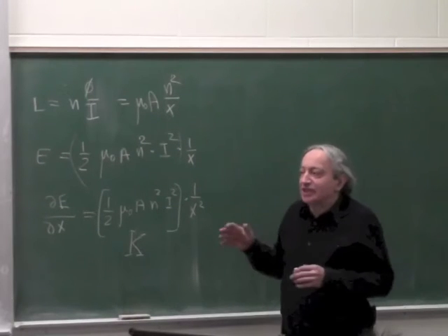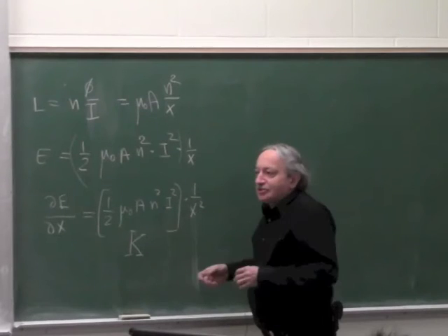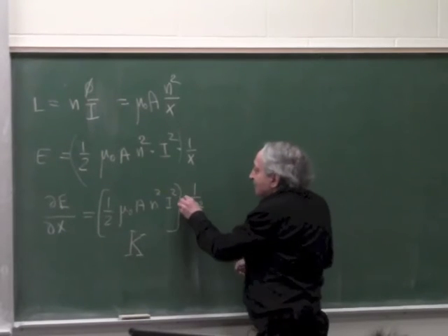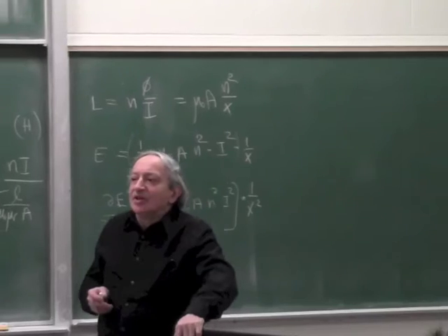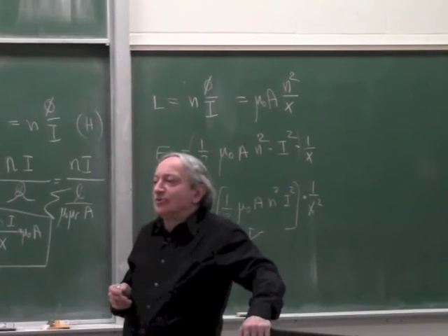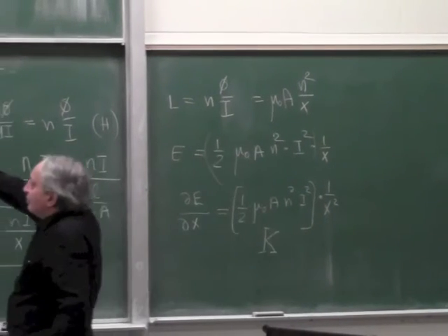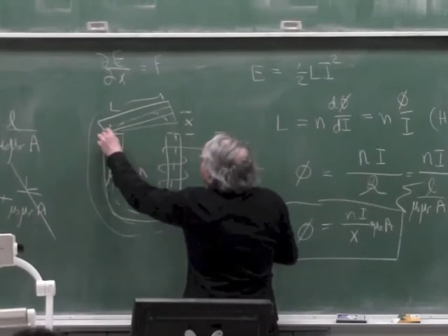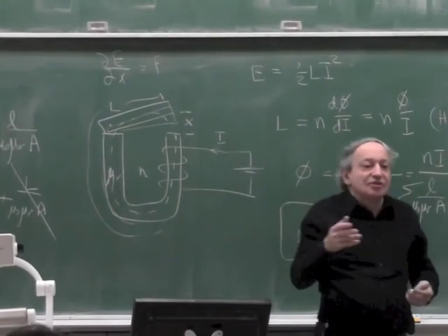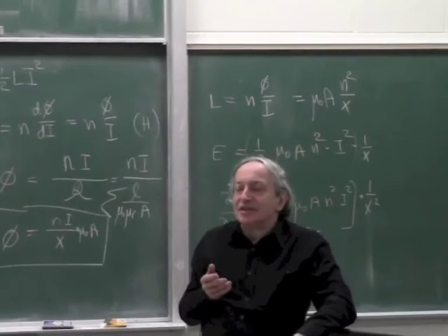It's not good in a servo system when actuators are not linear, but it doesn't mean they can't be used. Now, can somebody intuitively understand why it's not good when an actuator in a servo system is not linear, say with travel? What this means is that if x is half, the force will be 4 times, so the force will be nonlinear with travel. Now, why is that bad in the servo system actually?